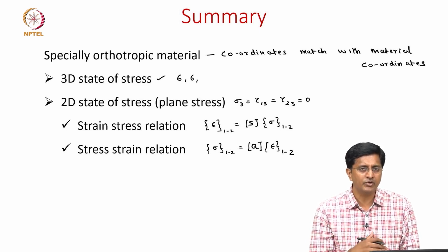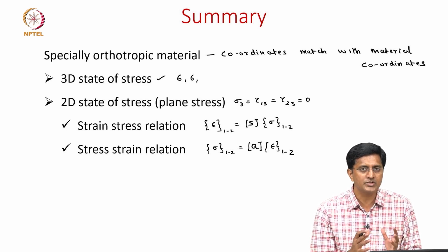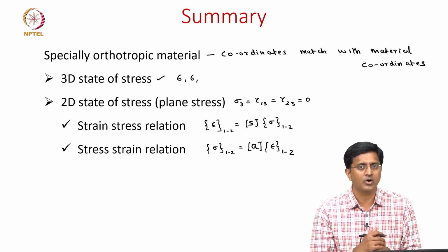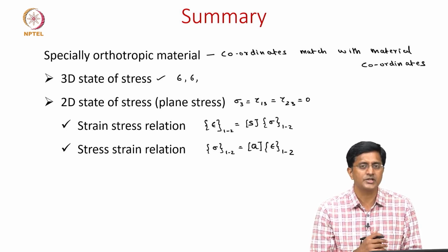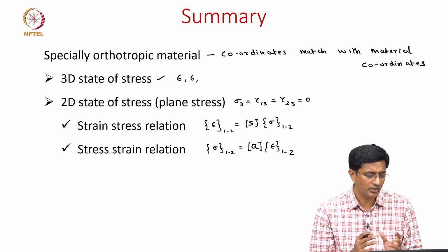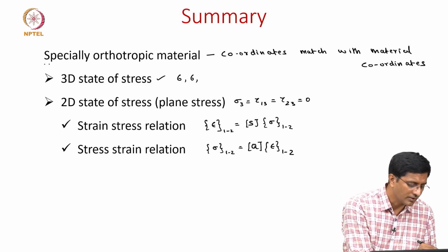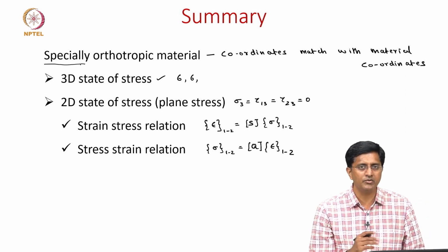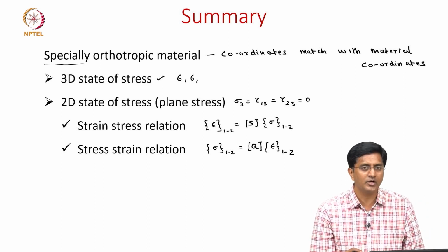So, in the next video we will look at, if the material coordinates we have chosen are different from the coordinate axes, how the stress strain relations change. In other words, instead of looking at a specially orthotropic material, we will start looking at a generally orthotropic material, which is most common in general applications.